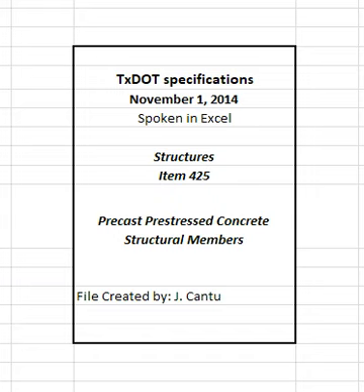3.2 Packaging, storing, and handling of prestressing steel. Protect prestressing steel against physical damage and rust or other results of corrosion, from manufacture to grouting or encasing in concrete. Prestressing steel with physical damage will be rejected. Replace any reel containing broken wires. Provide wire that is bright and uniformly colored, without foreign matter or pitting on the surface.